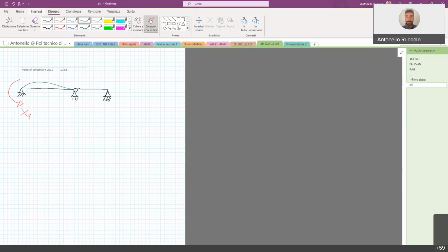So we have a bending moment applied in the first node of the structure. The deformation associated with this one, we have in this case rotation phi A1, because it is the one associated to the first static unknown, and it is equal to x1 times L, and in this case, L, as before, is 2L, because it is the length of the beam, over 3 E iota. So 2/3 x1 L over E iota.